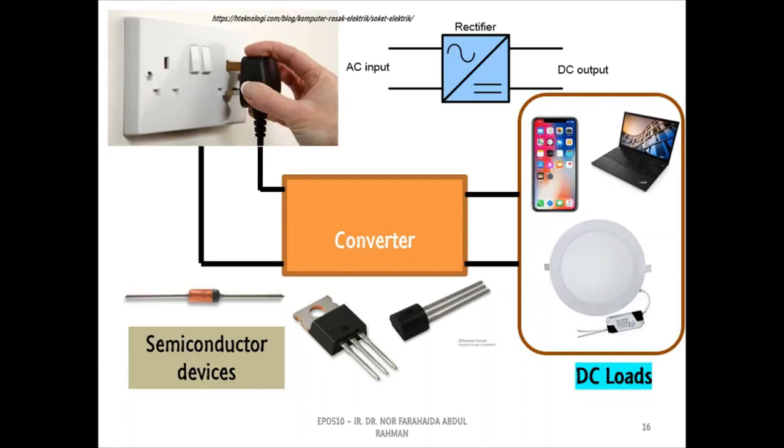Ideally, the rectifier converts sinusoidal AC voltage to constant DC voltage. Unlike low power electronic circuits, this converter usually operates at the grid power level and frequency. There are single-phase and three-phase converters connected to the single-phase and three-phase power systems, respectively.